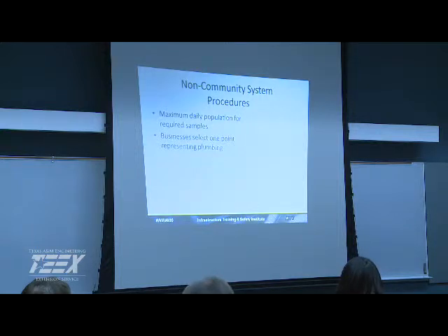So if you are non-transient, then you do need to make sure that you select an appropriate place in your business. Don't use the sink area where the mop sink is. Think about your process. One of the big issues they were having in some of the locations is the blending valves. A lot of the kitchen sinks are going to a blending valve now instead of two independent valves. So if you don't really isolate it well and just pull off the cold water side, you're possibly pulling out of the hot water side. That can be an issue for you for your bacteriological samples. So it's just thinking about your sampling techniques. Where's the good place to pull it?